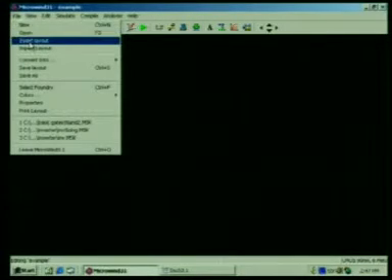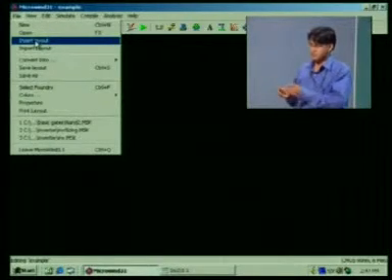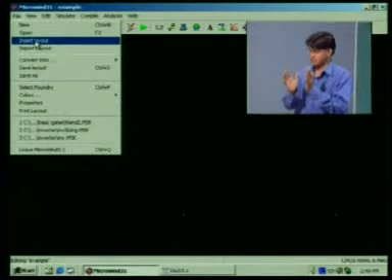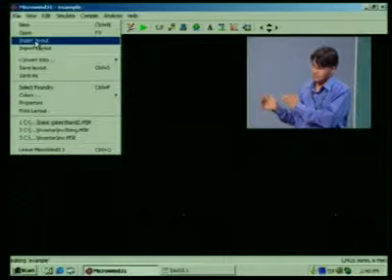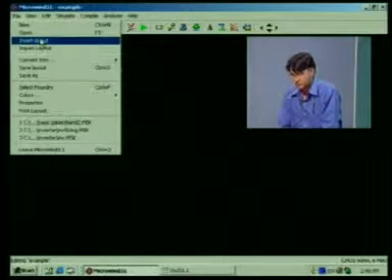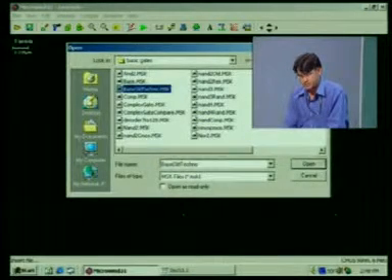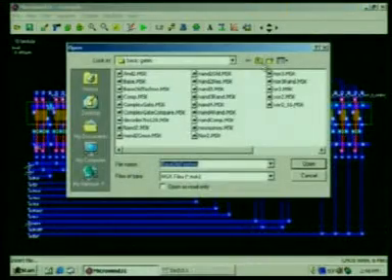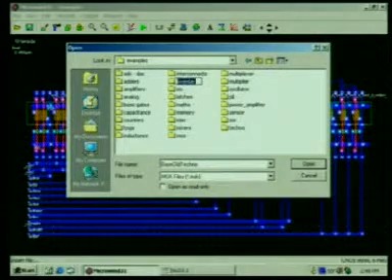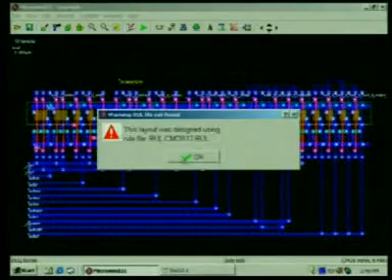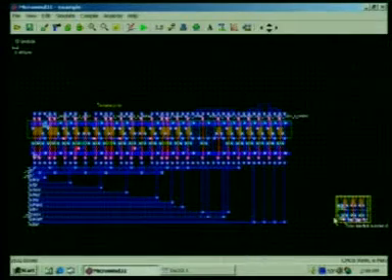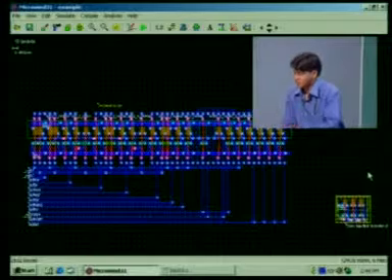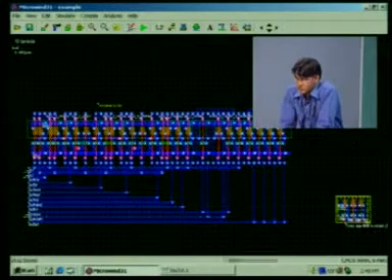Even there is one thing, you can insert layout. Suppose there is a big design, so you need to add different modules. Just partition that, create one module, then save that, again create a second module. In this way create the complete project, and after that use the insert layout option, and just insert this, and again you insert something like an inverter, like this, and then there is some algorithm for optimization, for interconnecting, and then we have to follow that one.